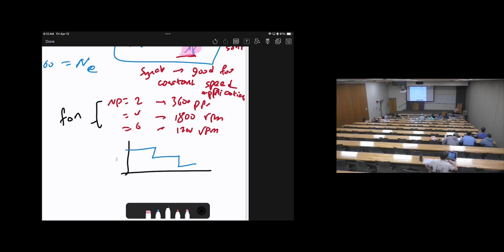The good thing about it is lighter weight, smaller size, higher energy density, and higher efficiency. And all of it is part of the three-phase synchronous motor. It's a special case, or a modified version, but it's actually AC. It's called brushless DC, but it is AC, and it's three-phase. So, again, we have different cases, different scenarios.